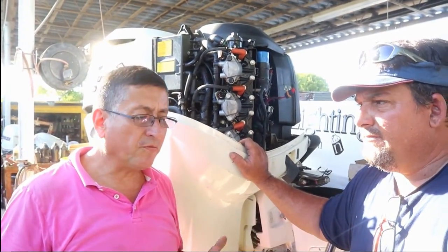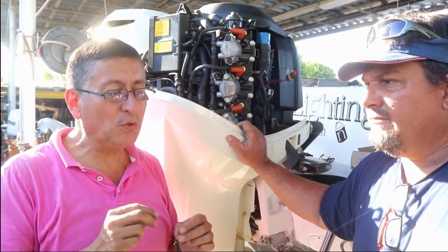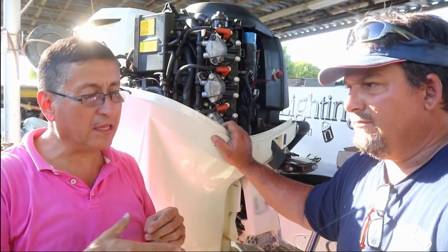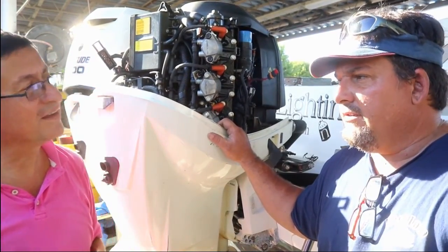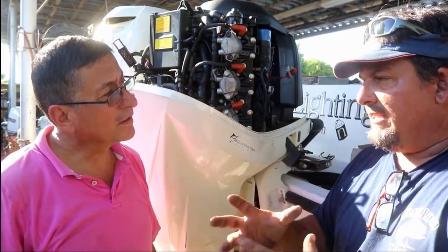Danny, in other types of engines, especially in diesels, I prepare a lot of tools when I check the sensors. And normally I use old harnesses, I cut them. Do you have the same technique here? Absolutely. Old harnesses are like gold. You can take the harness and make test tools out of it.